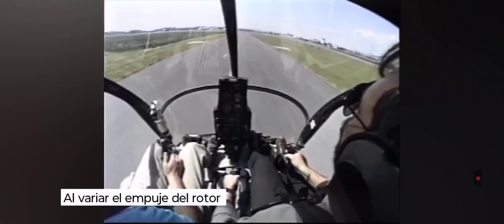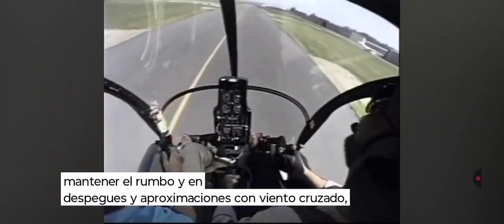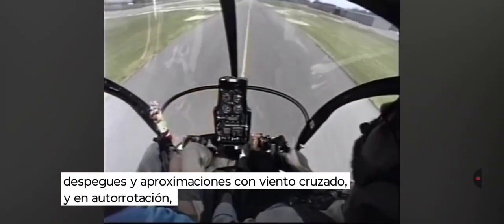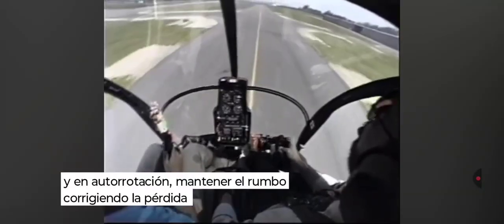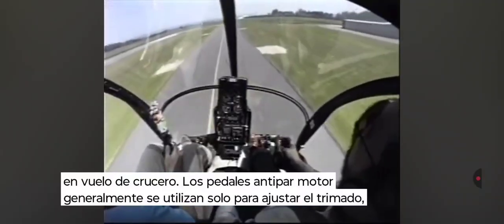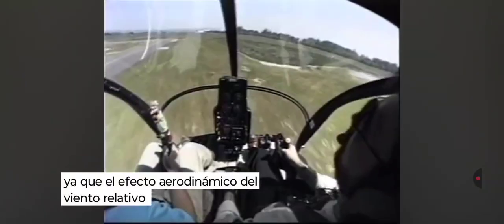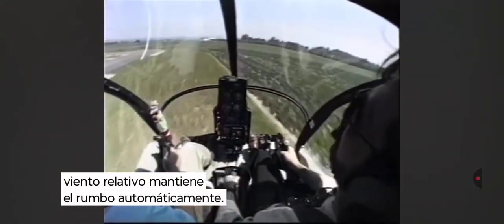By varying the thrust of the tail rotor, we can change heading during hovering operations, maintain heading in crosswind departures and approaches, and, in an autorotation, maintain heading by correcting for the loss of torque. In cruise flight, the anti-torque pedals are generally used only to adjust trim, since the streamlining effect of the relative wind does a good job of maintaining the heading for us.